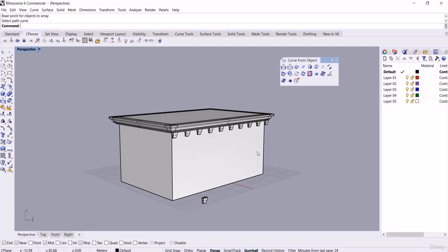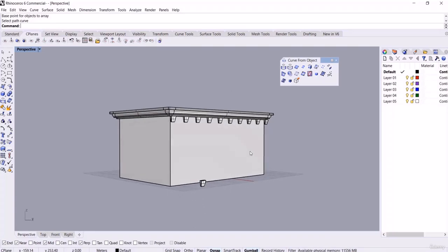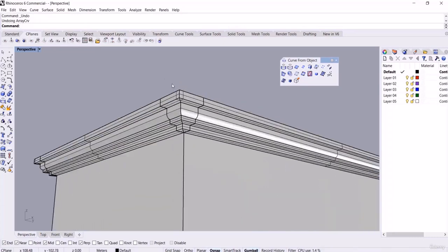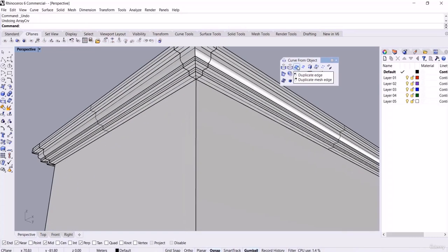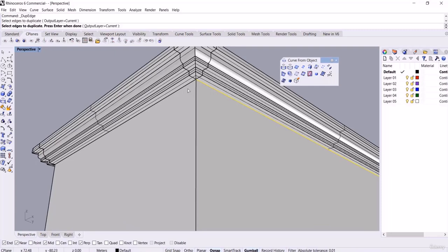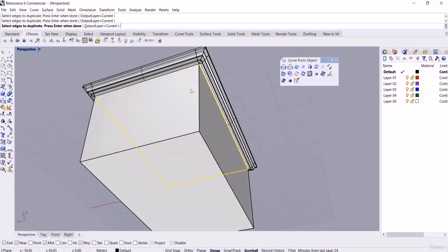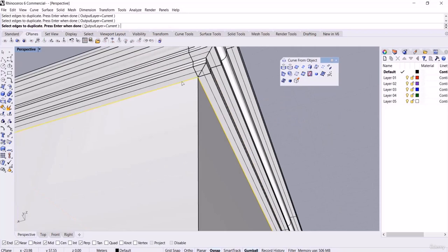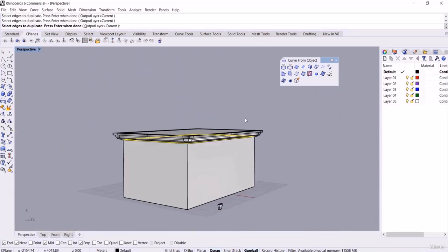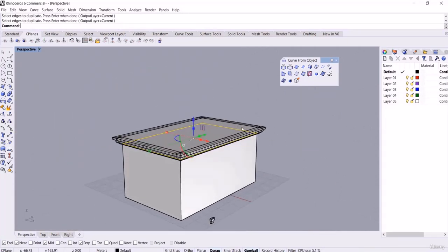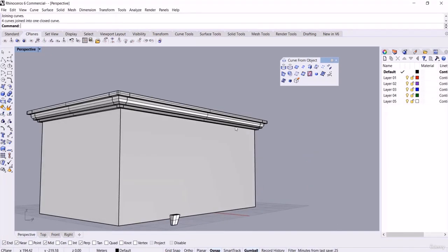As you're concerned, we didn't have a chain edges option to select the other edges of the chain. In this situation, we have to duplicate the edges because we do not have the chain edges option in the IsoCurve command. So I duplicate the edges, check it out, and as they are selected, I join them.